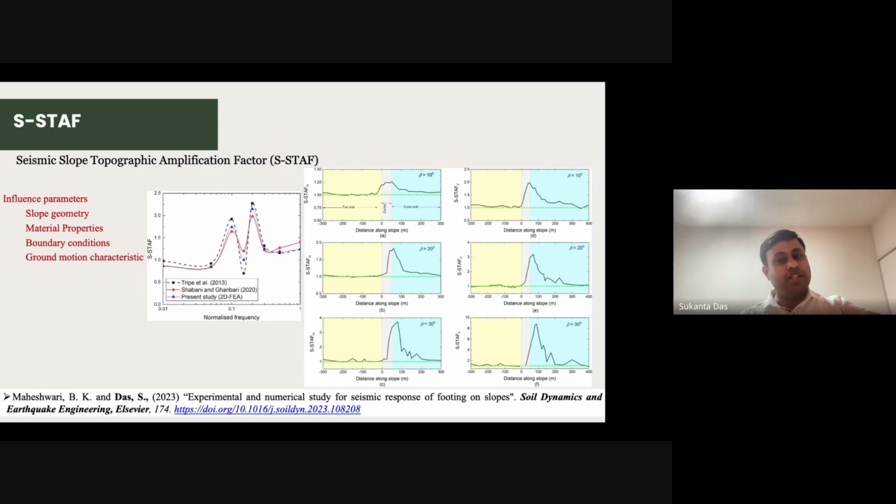In the Haiti earthquake of 2010, the Noto earthquake of 2024 and others, and the Northeast earthquake, some researchers noticed that in ridged or hilly areas the amplification is quite high. The amplification recorded at the station on the hillside compared to the other side is 8 times, sometimes more.